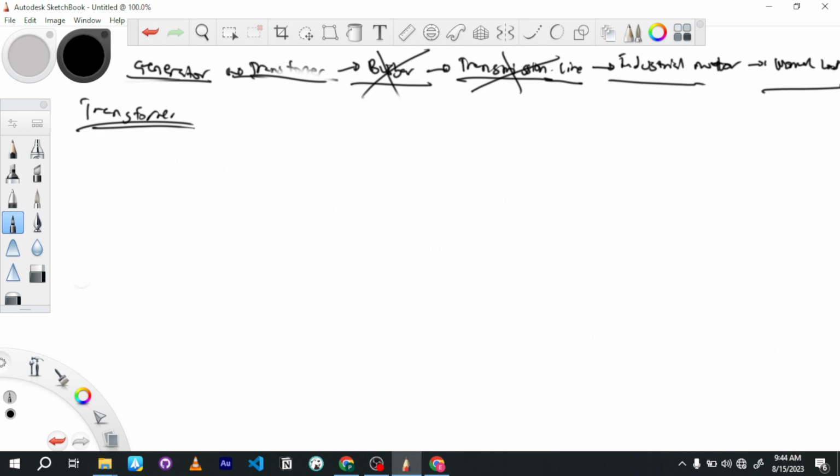You understand? So what goes on here is that you measure the current before it enters, you measure the current after it enters, then you just check if they're the same or generally in the same area. This is a unit protection. So whatever happens outside, let's say there's a fault current outside, it doesn't really affect it, right?